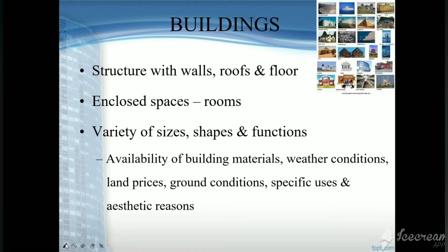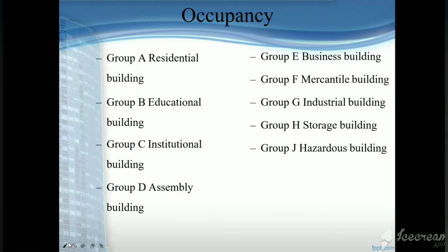According to National Building Code of India 1970, building is defined as any structure for whatever purpose and of whatever materials constructed, and every part thereof whether used as human habitation or not, and includes foundation, plinth, walls, floors, roofs, plumbing and building services, balcony or projection, etc.